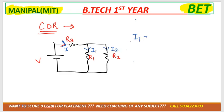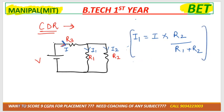So let us consider the formula for I1. We can directly get it by using the current division rule. So I1 is equal to, what is the formula for this? Total current, that is I, multiplied by the opposite resistance. So for I1, the opposite resistance is R2, divided by R1 plus R2. Okay, this is the formula we get from the current division rule. Similarly, can you tell me, all of you, the formula for I2?